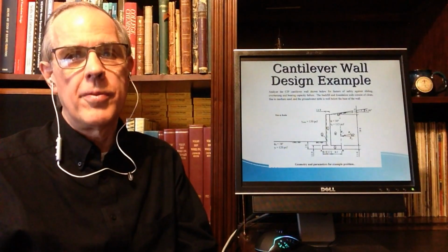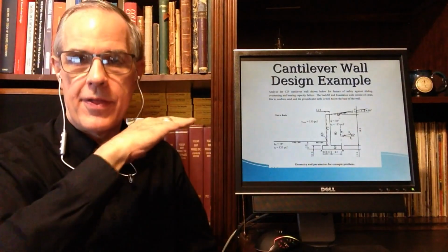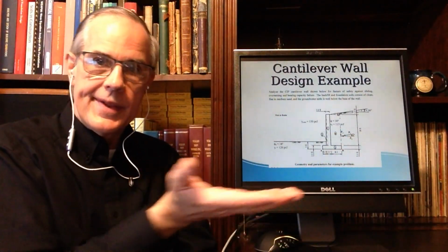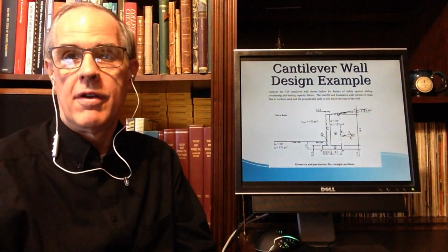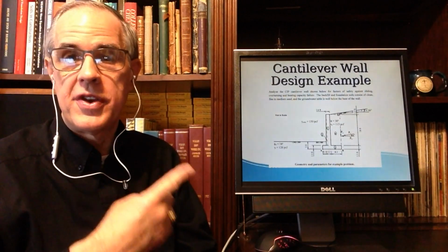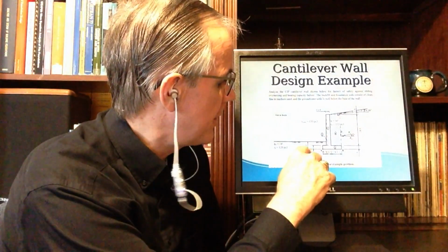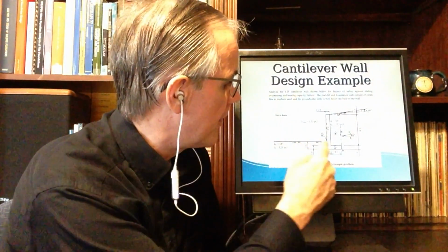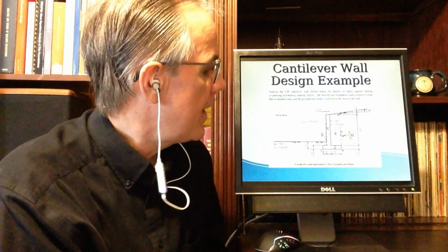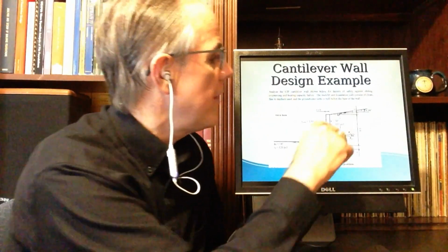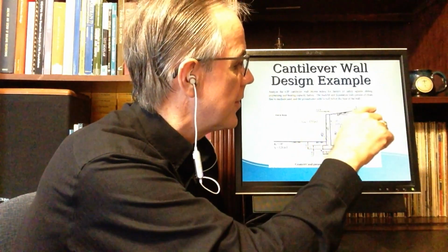That's important because normally in bearing capacity analysis, you've got one of the tricky things. Remember in bearing capacity, you had this nice soil, and then the base of the foundation, and the distance from there to there is D sub f. Now we have this mess where you've got two different depths. Well, it's easy to solve that problem. The D sub f is right here on this side of the wall, not over here. We don't worry about this; we worry about this. Then, if that wasn't enough to make life miserable, we've got this 10-degree backfill slope, and that gives a little extra